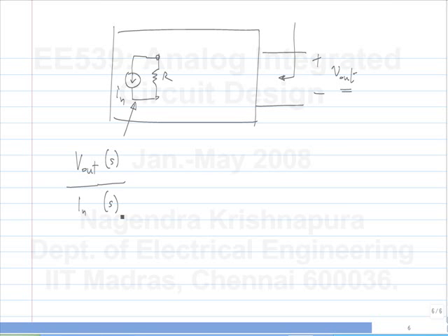So this gives me, if I had a source IN, I know what effect it will have on V out, as a function of frequency. So this is the transfer function from the noise source IN to the output voltage V out. Then what do I do?